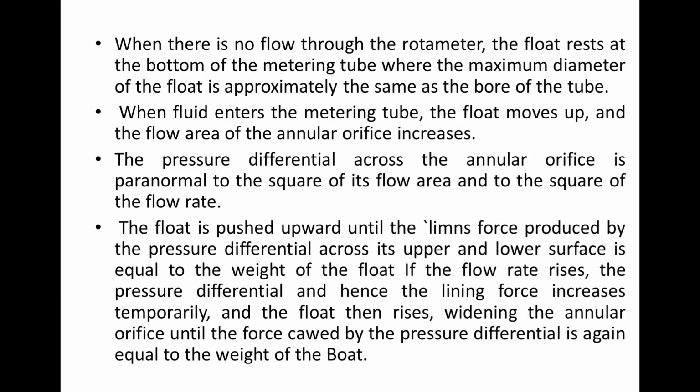The pressure differential across the annular orifice is proportional to the square of its flow area, because the cross-sectional area is indicating the measurement of the flow. That is, a square of the flow rate. The float is pushed upward until the drag force produced by the pressure differential across its upper and lower surface, because there is a change in the cross-sectional area at the top and the bottom.